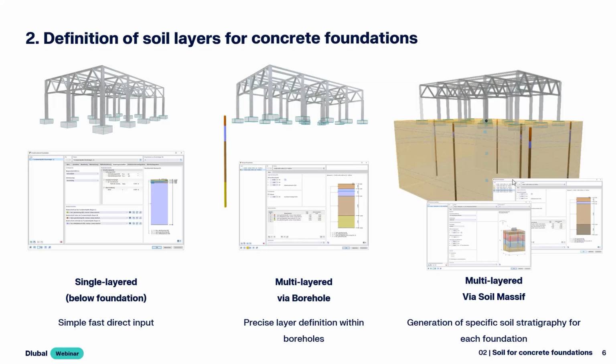And there you can define the boreholes wherever you have them from your report, and you can generate the soil massif, and then automatically every concrete foundation gets the soil stratigraphy that acts below that foundation.